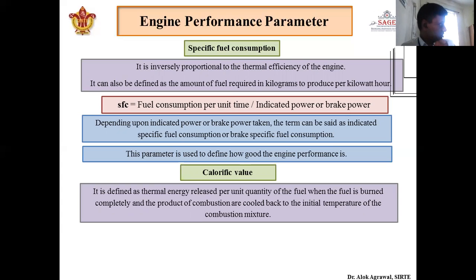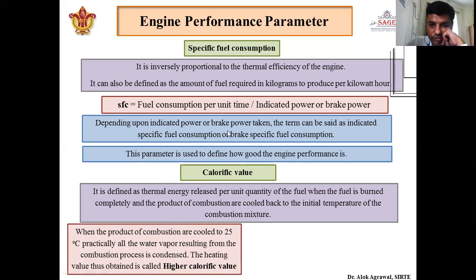So this is the calorific value of the fuel. It can be defined in two categories, higher calorific value or lower calorific value. When we take the products of combustion back to the normal temperature, that is, we consider 25 degrees centigrade, then the amount of energy released is called higher calorific value.